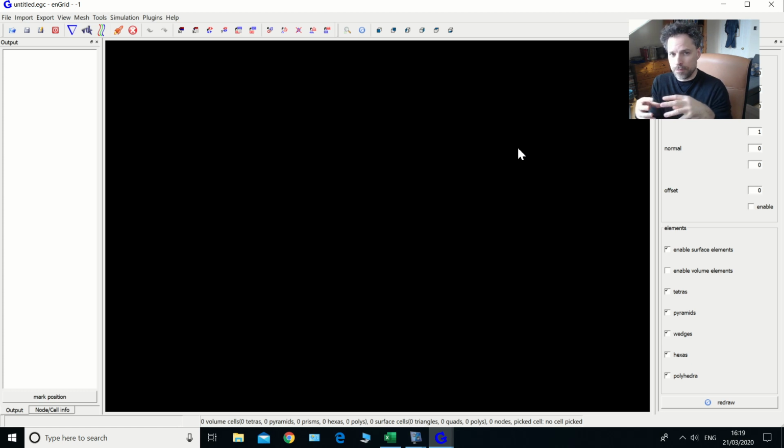Then we're going to make the volume mesh in the middle, and then we're going to subdivide the boundary prismatic layer into however many layers we want. This is why you get a good behavior with the boundary mesh, because we don't move the volume mesh inside like we do in snappyHexMesh when we add more layers, which eventually causes horrible problems with orthogonality and skew depending on what the geometry is like. Unless it's very smooth and absolutely perfect, it's really bad.